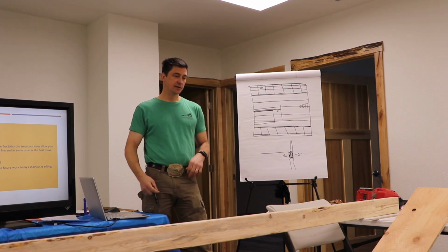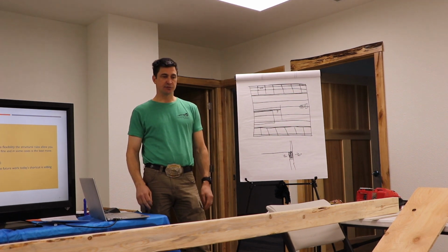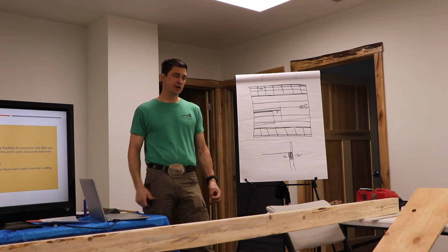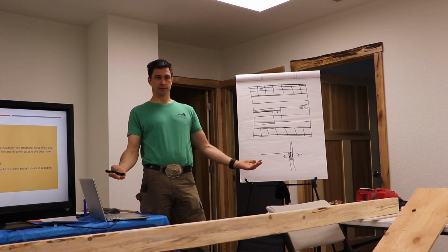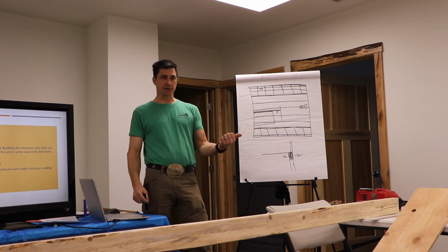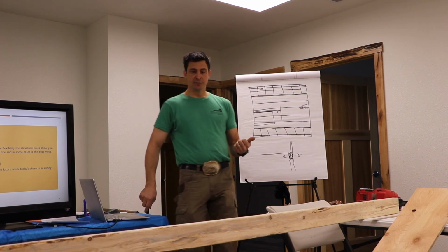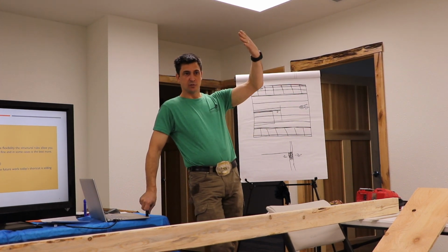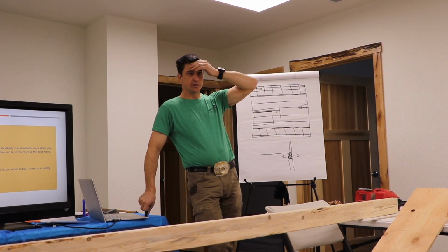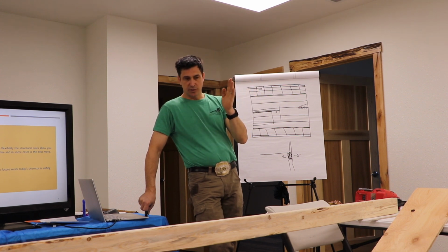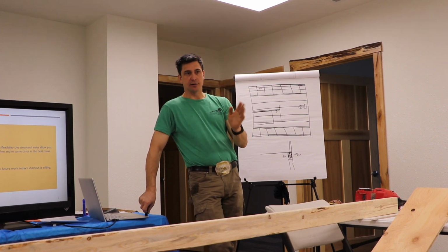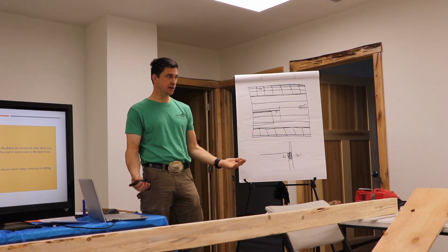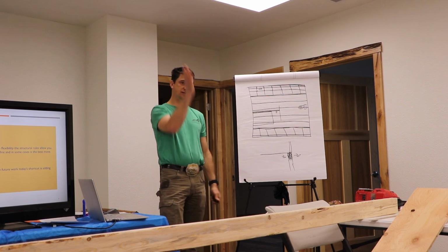So that's the kind of shortcut that drives me absolutely crazy. Like, oh, we're just going to throw a piece of backing wood on here. Why? Does it give you a better product? No. So the ladder blocking that I like to see to hold where a wall intersects another one makes your corner straighter than running backing wood. Because studs can be crooked, right? You guys have all seen a stud that's as crooked as a snake.